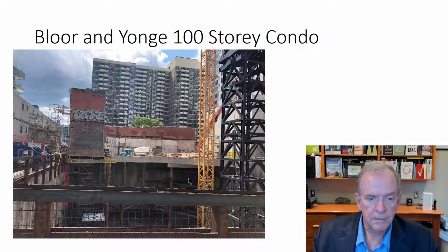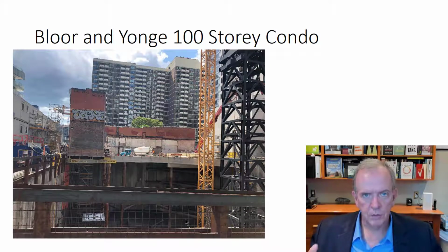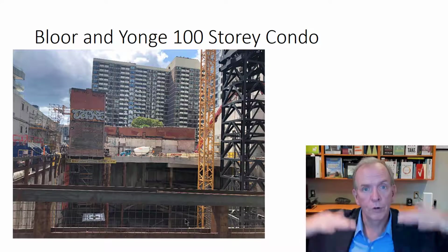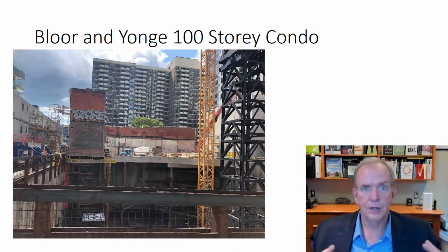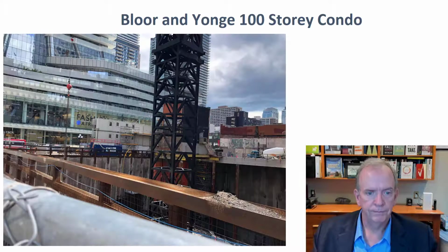So in this case, the bracing is on the interior. So that means you've got to build around it. All the while you're building around it, it's like a pain. It's in your way, and you've got to form around it, you've got to pour around it. Now, once the concrete floors at the different levels are in, it's not going to collapse at that point. It's fine. It's structurally sound. But during the process, this has to be done on the interior, so that makes it more complicated.